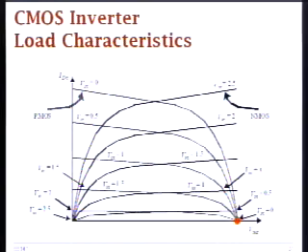So you start from here, V in is equal to 0, then you move over to this point, then you move over here, V in equal to 1. So you see that for this initial case, when you start off from V in equal to 0, you make very little progress on the V out axis. And then going over here from 1 to 1.5, you jump over a huge step on V out. So that's basically the region where both of your transistors are in saturation and you have a lot of gain.